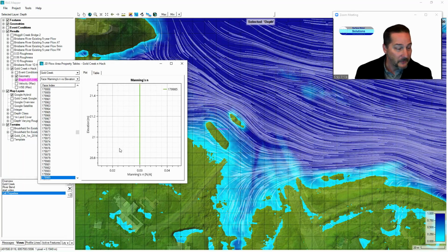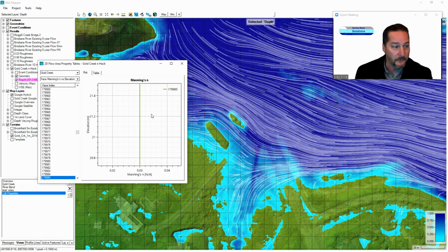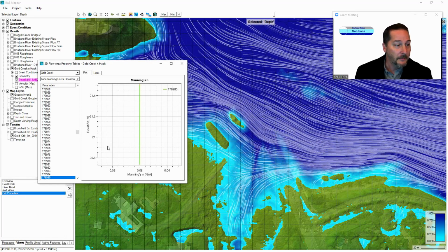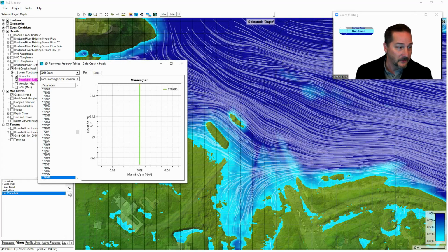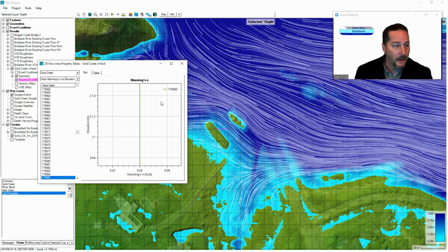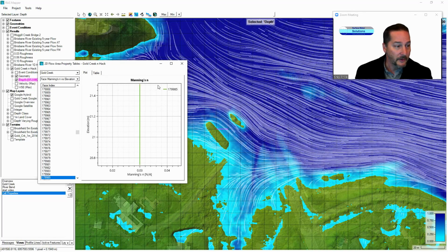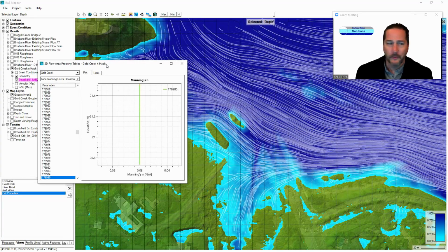Now, there is some software out there that you can use for 2D modeling where each cell or each edge can be treated with a depth varying roughness. And in this case, we have elevation, but this could be depth over here. And you might have a diagonal line, or you might have some thresholds where it's constant up above or below those thresholds. Well, why would you want to do that?